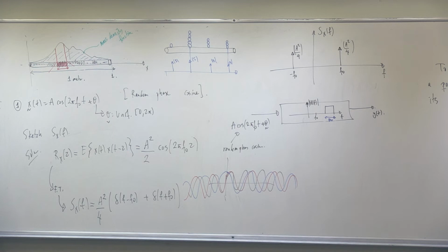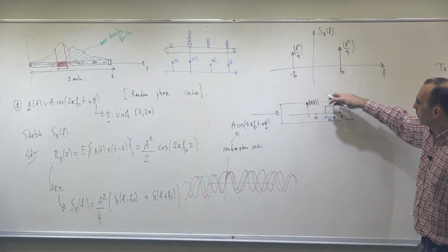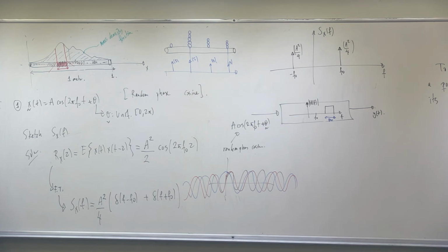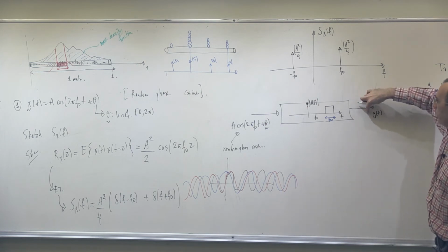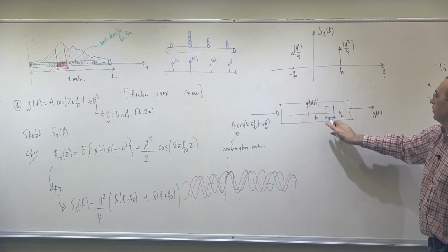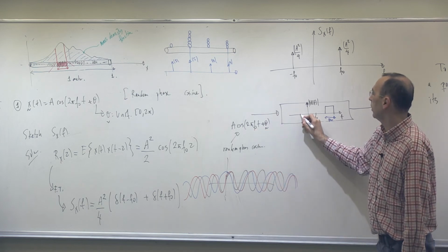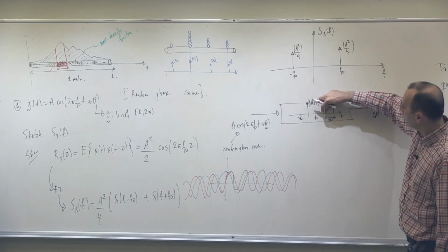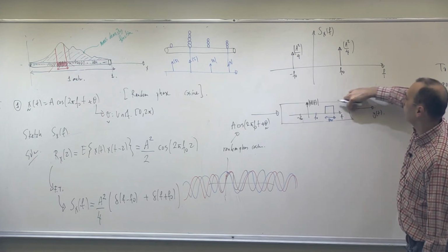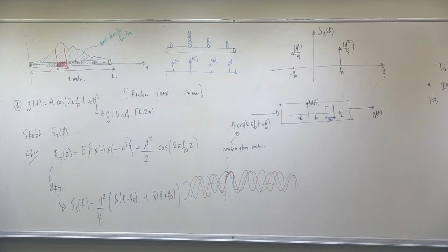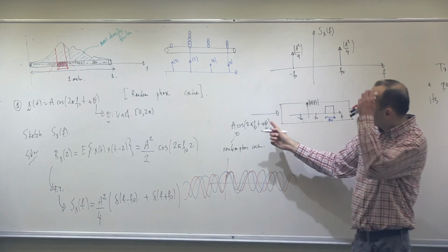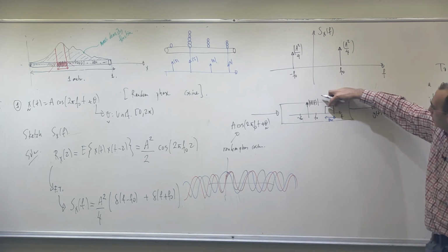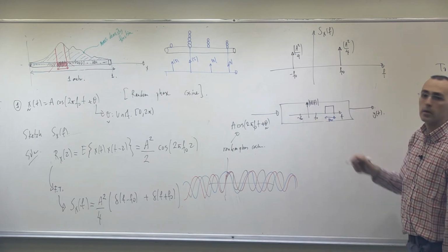Okay, so you don't know anything about random processes. So does this make sense to you? If I apply such a signal to this h of f box, and the filter is something like this, do you think I will have a non-zero output if the filter bandwidth does not include this frequency? So f naught is over here, minus f naught is over here. It shouldn't be, because this is an ideal filter, suppressing everything outside of this frequency band. That's the task of a bandpass filter. So whatever I select over here, it should be 0 at the output, isn't it? Because the passband of this filter does not include f naught. Okay, that is the idea.